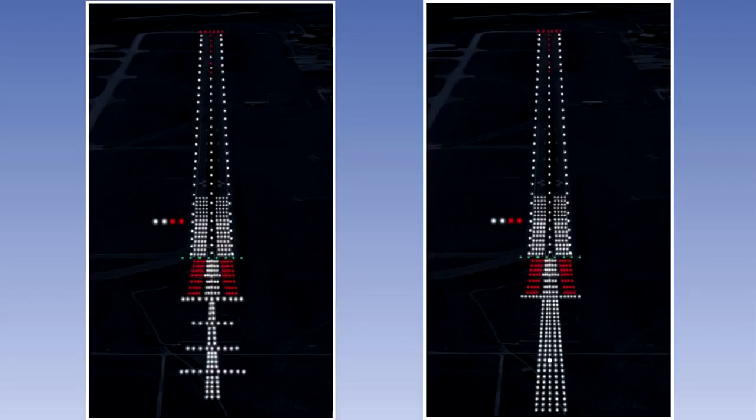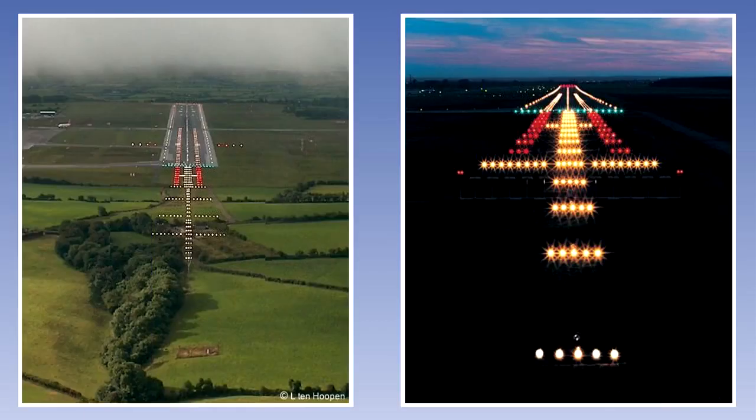At those aerodromes where Cat 2 and Cat 3 approaches are conducted, more complex approach lighting systems are installed to enhance the ability of pilots to achieve the visual criteria needed to complete a landing. You will find many variations of this kind of lighting, but they're all based upon the Calvert 5-bar and centerline or ICAO barrette lighting systems.